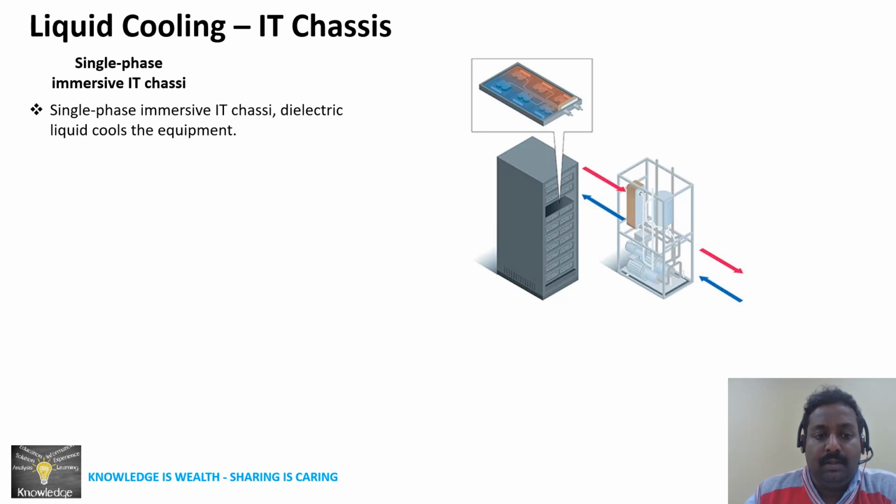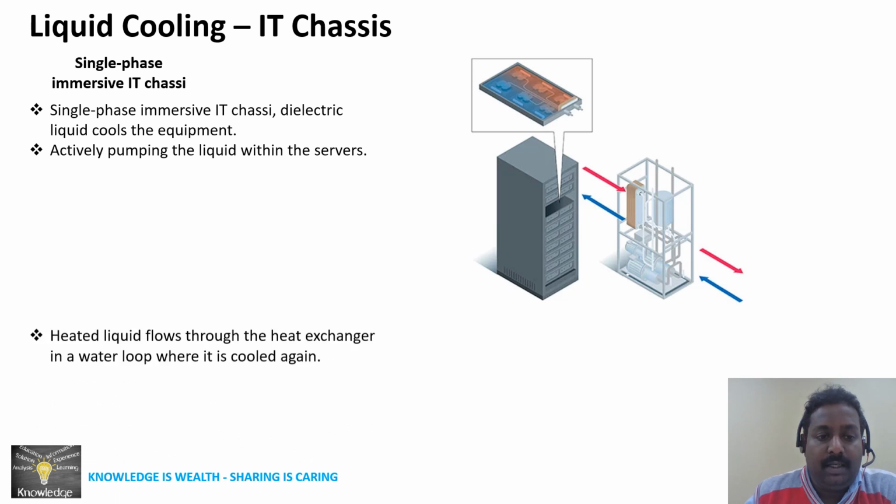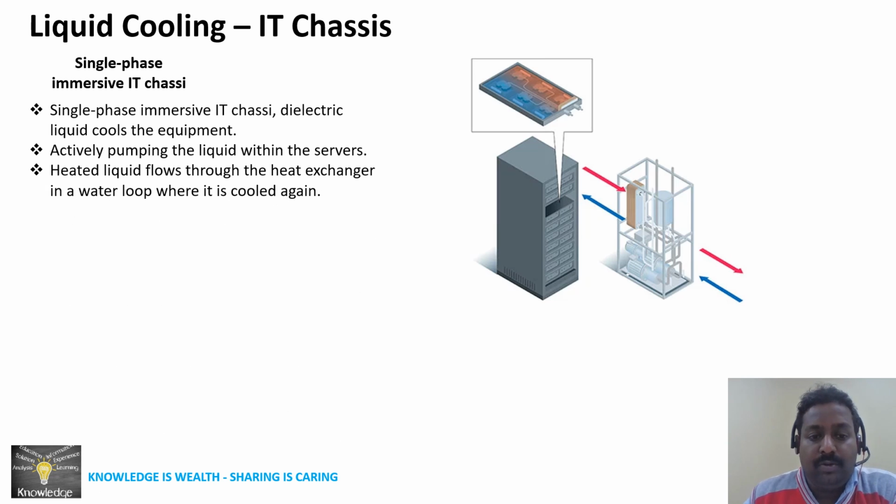So in single phase immersive cooling, the IT chassis is cooled by dielectric fluid. There is active pumping of liquid within the servers, and heat is carried by the liquid flow through the heat exchanger water loop, where it is cooled. There is a heat exchanger where this fluid will cool down again, and it will come back to the